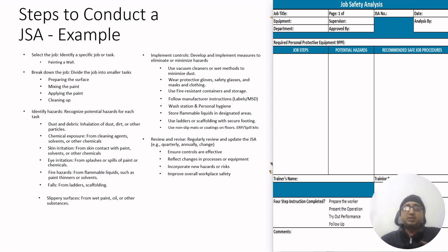Now, first, which hazards can we face in the lift plan preparation? During the lift plan, maybe our plan is insufficient or incorrect. Maybe the risk assessment we did is insufficient. Maybe the inspections we conducted are insufficient. Maybe the equipment we have selected is not the right one. Maybe the staff we are using is not competent. So how to control them?